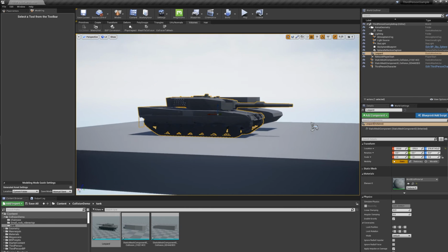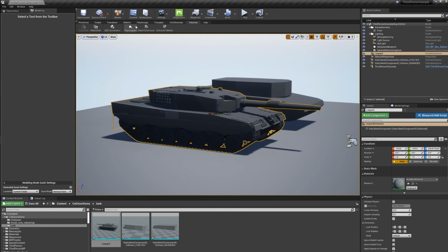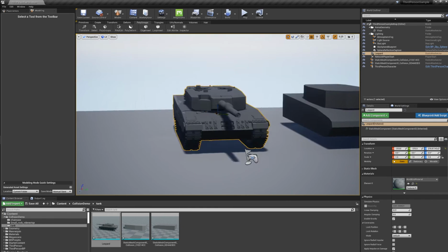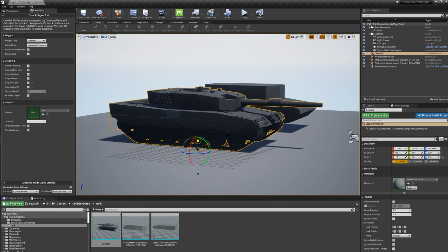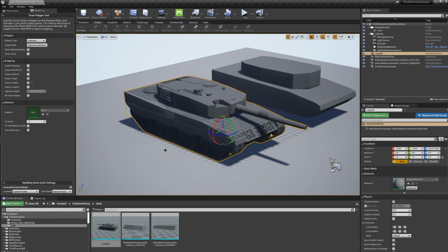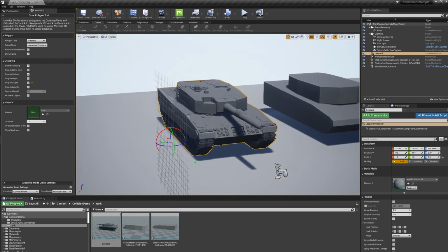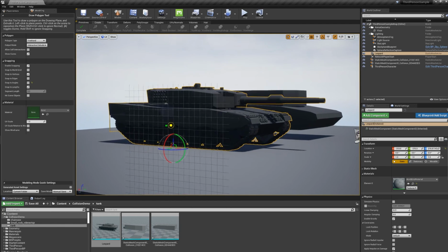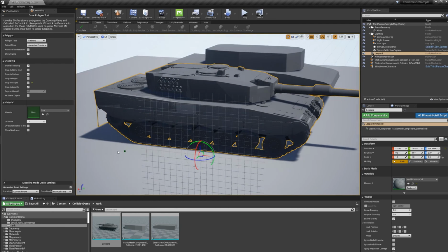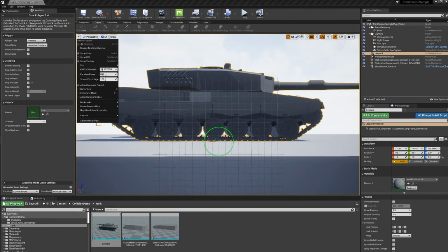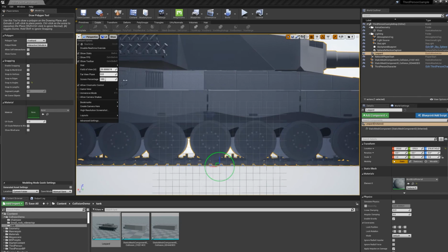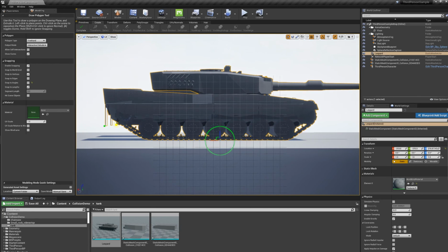And I'll just show again, we could use the method I showed before to capture the treads. I want to draw a polygon basically. So I'm going to Control-Shift-Click somewhere close, and then I'm going to hold Shift to rotate 90 degrees because I'm not sure any of these faces is exactly perpendicular, and I think this will just be easy. It's kind of dark here, but now if I just look from the side, one thing you notice is I've got my field of view here set quite low. This makes it easier to do this kind of thing.